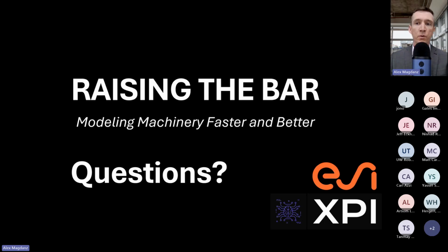Depending on what you're trying to do, it may be a matter of simply setting the right boundary conditions and allowing the solver to solve for the unknowns, or it may be a problem in which we actually use controllers or simply PI blocks or PT blocks to translate from the current scenario into the required inputs to achieve a certain output. Basically, we use a quasi controller to adapt the model to calculate the inverse solution. But I'd be happy to go through your specific problem with you and come up with a solution.